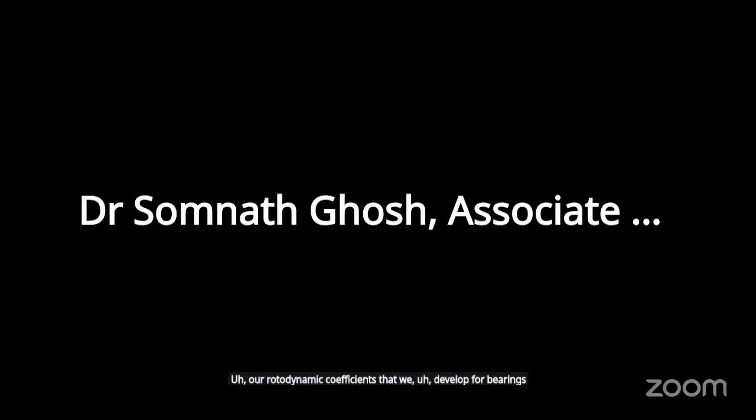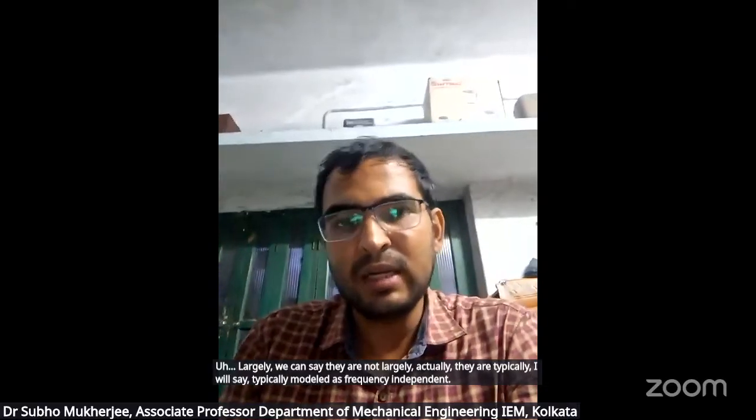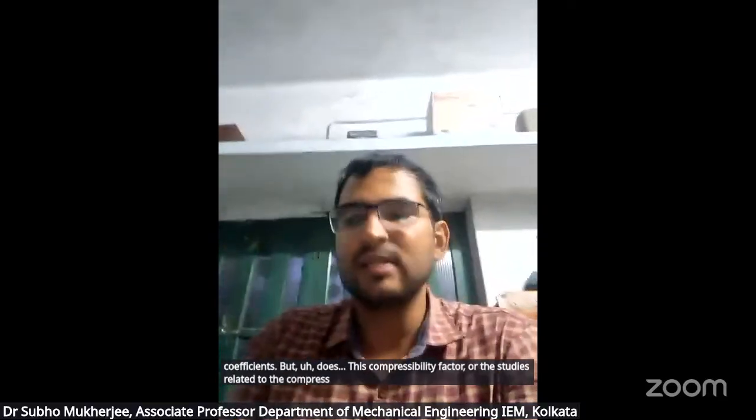Okay, Professor Ghosh. My next question to our open forum is this: largely we find that the rotodynamic coefficients that we develop for bearings and seals are typically modeled as frequency independent coefficients. But does the compressibility factor, or studies related to compressibility, affect the frequency dependency?